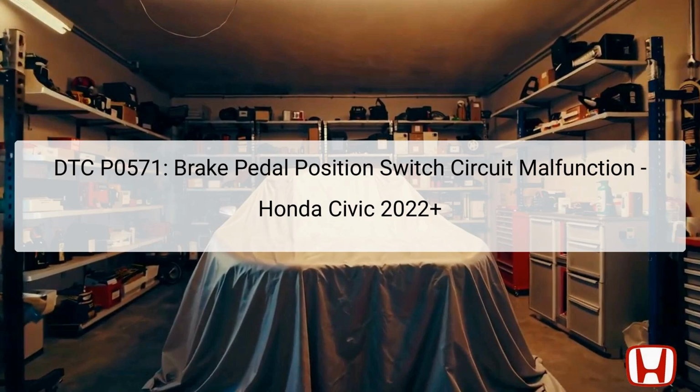The brake pedal position switch is crucial for signaling the PCM when the brake pedal is engaged or released, impacting systems such as the cruise control and brake light operations. A malfunction can lead to erratic brake light behavior or disable the cruise control system. Possible reasons for this DTC appearing can include the switch itself being faulty, issues in the electrical circuit, or problems with the PCM. Immediate attention is necessary to resolve brake-related issues for safe vehicle operations.